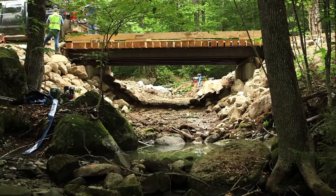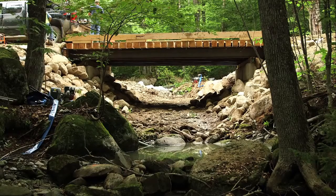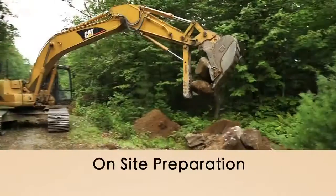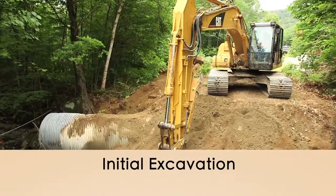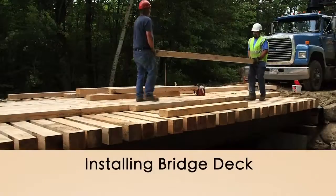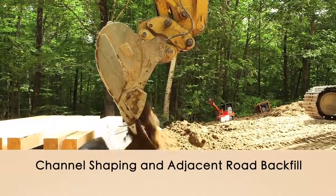The steps for this project and all stream-smart road crossing construction projects include the following: a review of the construction plans, water control, on-site preparation prior to construction, initial excavation, setting the abutments and establishing the stream channel, installing the bridge deck, channel shaping and adjacent road backfill.